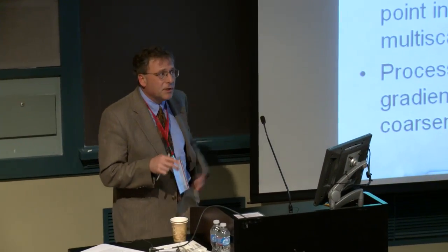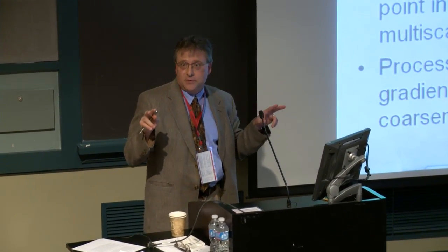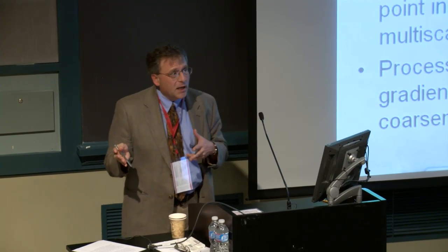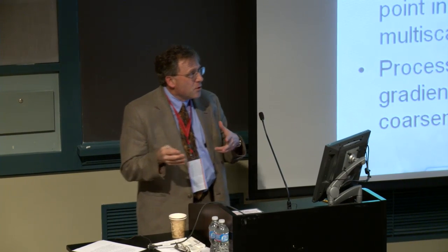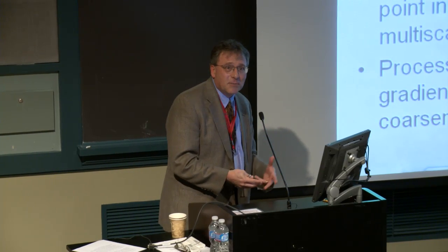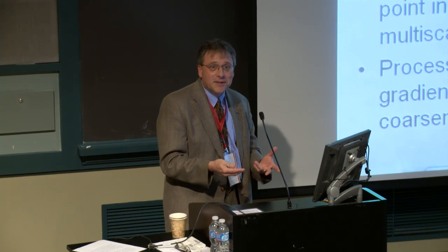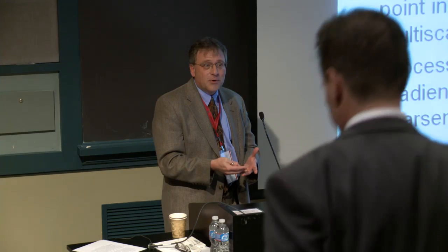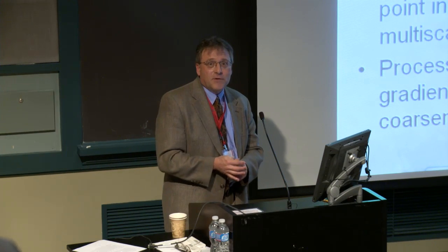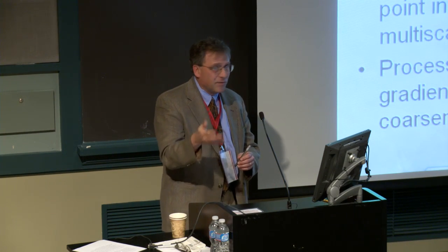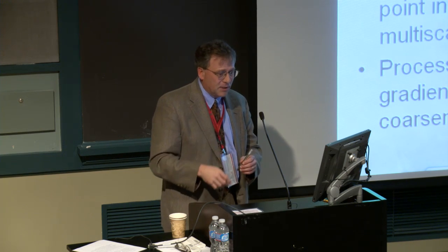And some of them are considered as extrinsic in nature, right? So something like a non-metallic inclusion, you wouldn't necessarily call that an intrinsic microstructure feature. It arises due to the process where you're forming ingots, right? So you have to understand the life cycle of the process route, and structure and property relations.